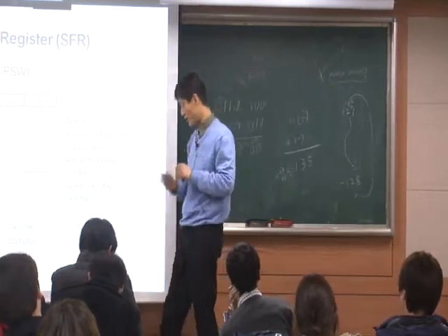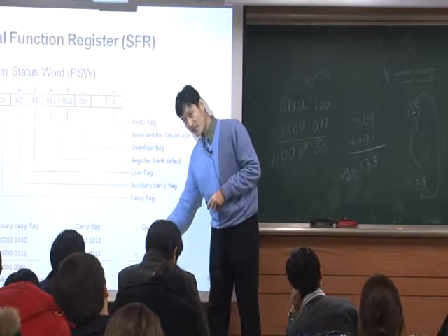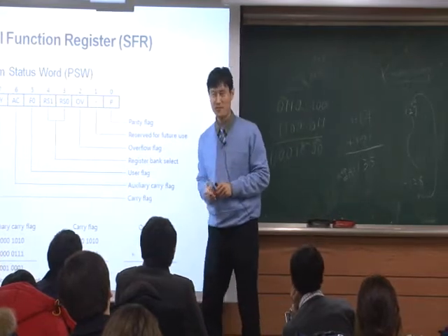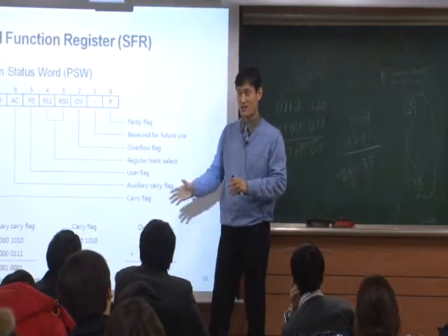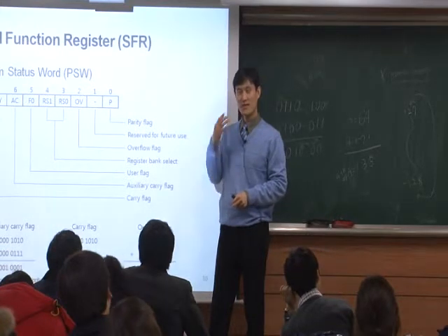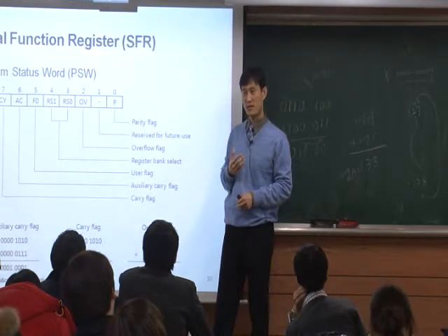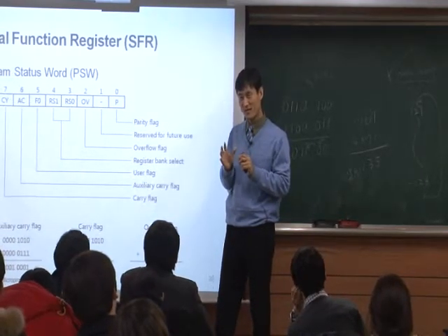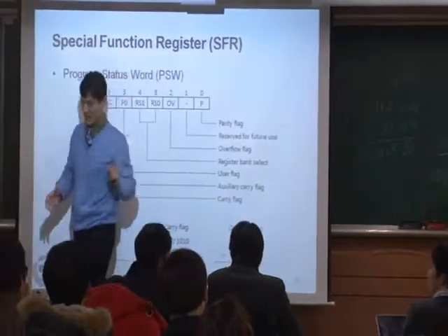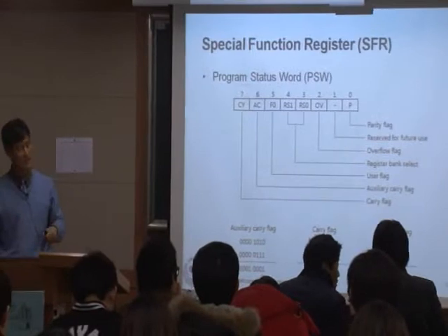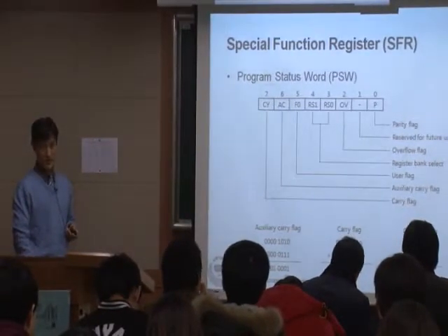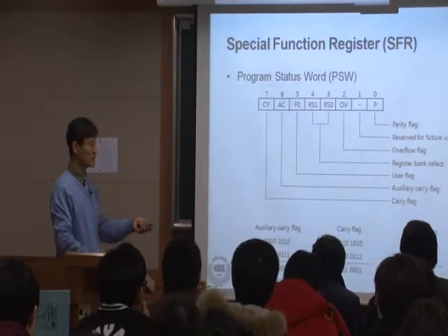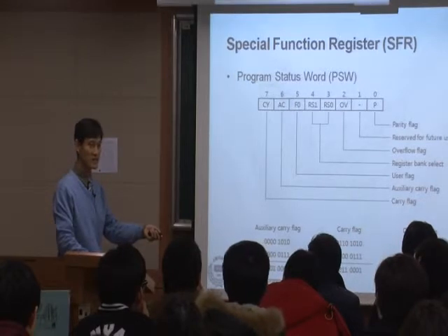However, the microprocessor doesn't know. The microprocessor simply sees the MSB 0, 0, and you add 0, 0, but the output becomes 1: overflow. They don't care about unsigned or signed. Okay? Think from the microprocessor perspective. The microprocessor is very dumb, very simple. Okay? Very simple. When you read it, if you want signed or if you want unsigned, it's up to you. What they do is just calculation, but what we read is up to ourselves. The calculation is simply binary calculation in this case, right?